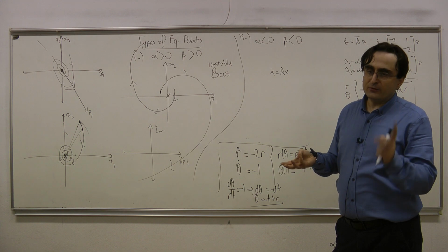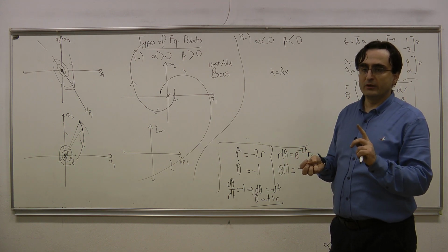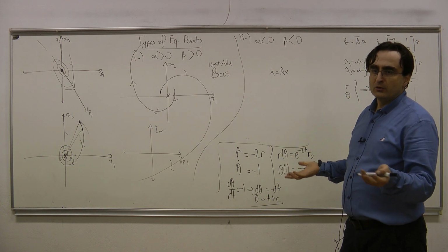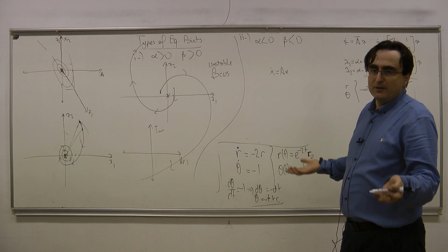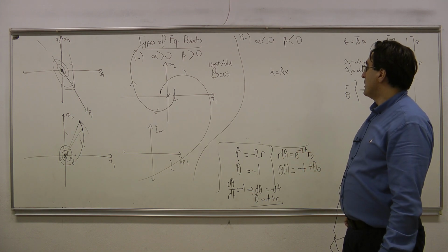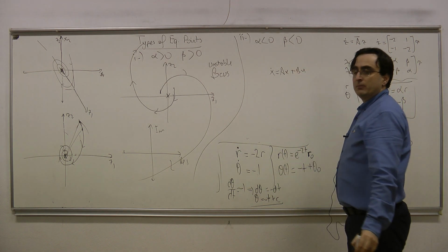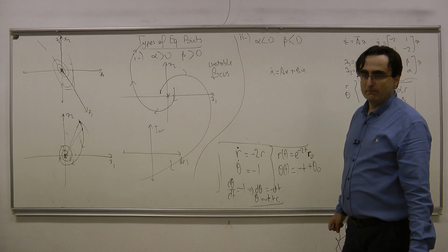And the transfer function is an input-output descriptor for a linear system. Here in this system, I don't really have any input, so I cannot talk about its transfer function when the input is not defined. But I know that if I define an input to the system, then the poles of the system would be the eigenvalues of A. Okay?